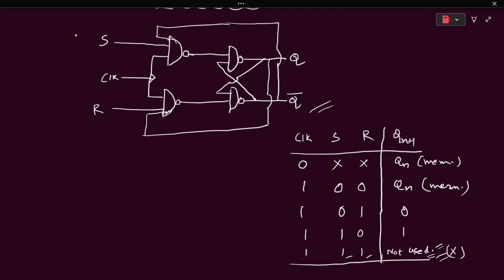This circuit is a bit hazy, but I think it is legible to all of you. This is the circuit of a JK flip-flop, and when we use the 3-input NAND and feed the final outputs back into the inputs of the previous stage, then this S and R change to J and K. Okay, so this is the circuit diagram or design of a JK flip-flop.